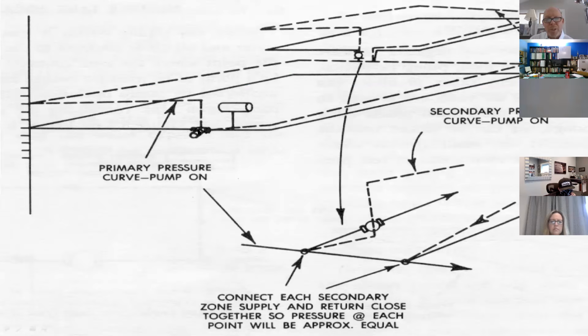And it increases when the pump turns on because of the location of this expansion tank, which is actually another class we have coming up later this week. As that differential is starting to decline because of frictional resistance, the secondary circuit pump references that pressure there, makes a decision, and adds it to the secondary circuit's pressure.